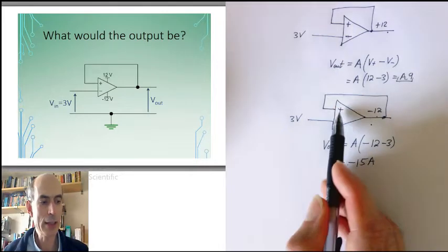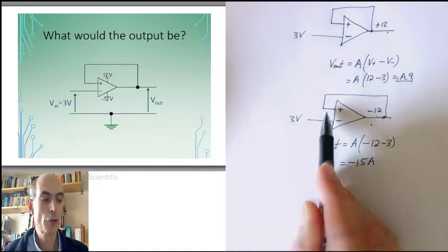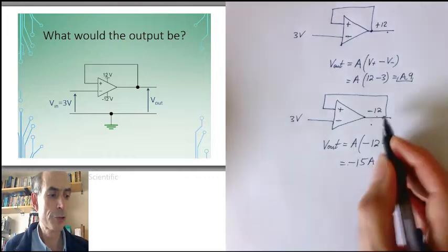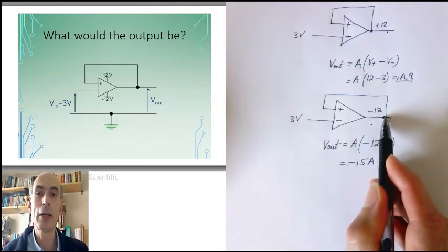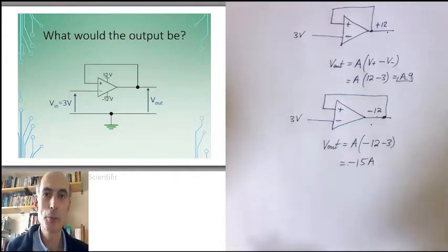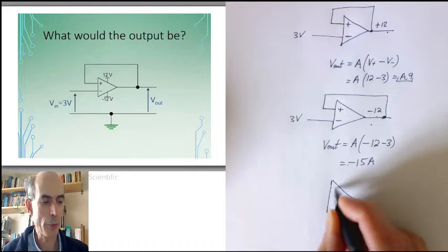So instead of connecting the non-inverting input directly to the output, we would only feed back a proportion of the output. The standard way to get a proportion of an output voltage is everybody's favourite circuit again, the potential divider. So the circuit that we'll be investigating is this one.